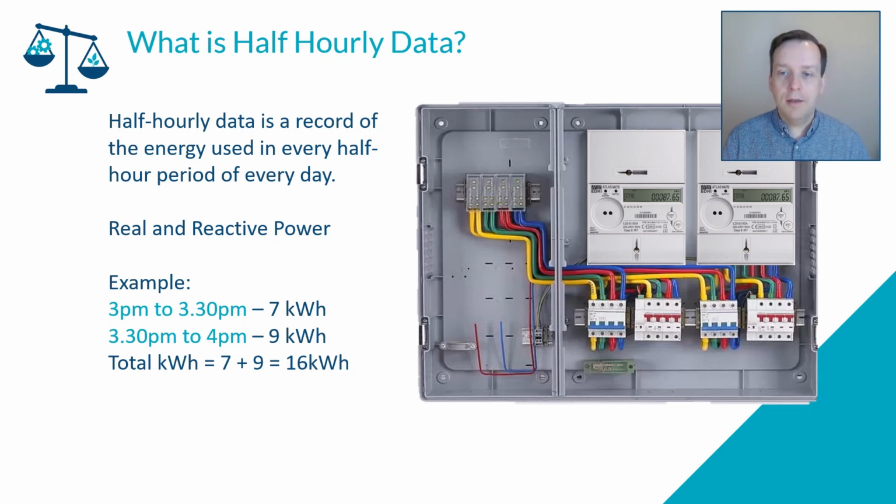So this on the right, the image on the right here, we have two half-hourly meters, and depending on the voltage level, you certainly at above 132 kV, depending on your metering point or your contractual billing point, you may have actually 2 meters, main and backup, and it's simply redundancy, or sometimes called main and check meter, just to make sure both are reading the same, because obviously electricity is a very valuable commodity, and if you're using megawatts, the cost difference from small variances will certainly add up over the course of a year.